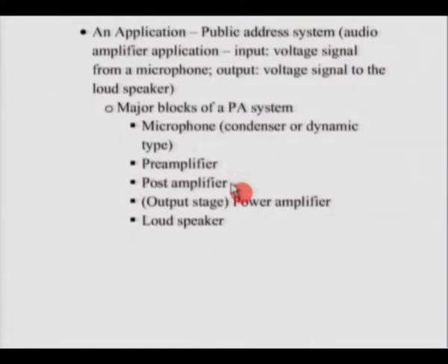Now if you have a discrete amplifier, that is where you can think of maybe using a common emitter amplifier. So we see that common emitter amplifier, because of its low input resistance, cannot be directly used along with a sensor, especially with a microphone or so. You could use it in between stages. And finally, in a public address system, you need to develop the signal across a loudspeaker, which is extremely low impedance, 8 ohms, 16 ohms or so, and that is where we use a power amplifier. This is one of our lectures later on.